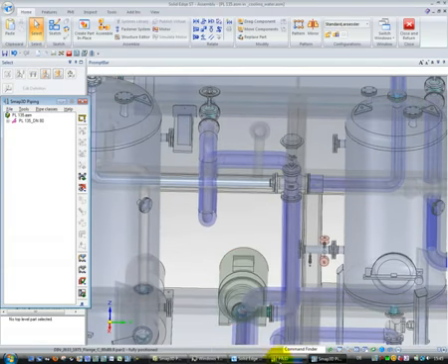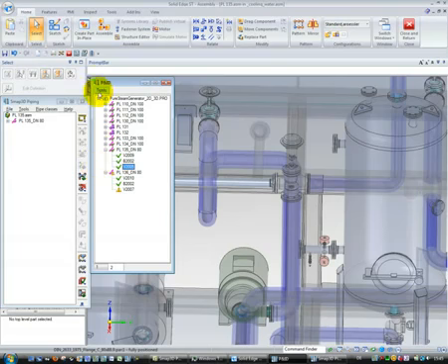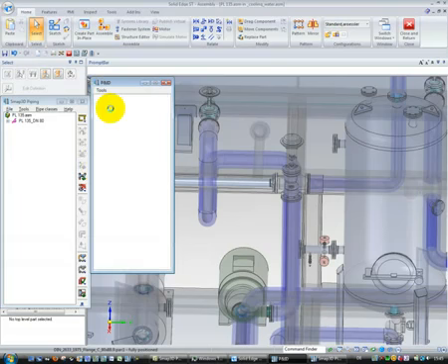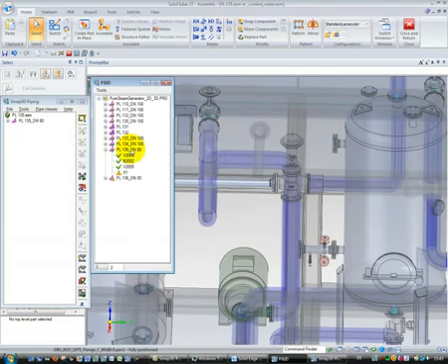In 3D we open the P&ID connection, and here we refresh the content. And when we have the result from the refreshing process, we see that there is now an additional component, and that this additional component is a reducer component. So now we have transferred the knowledge from P&ID to 3D that we have to produce a reducing or expanding situation on these connections. And this we can do now with our applications.